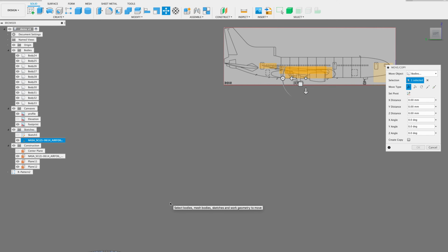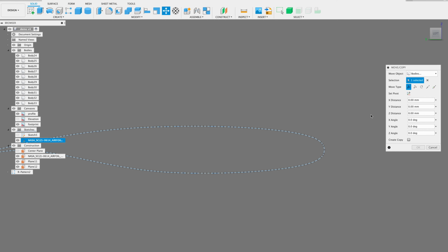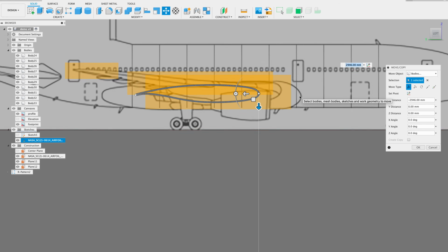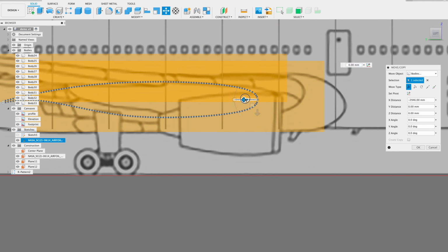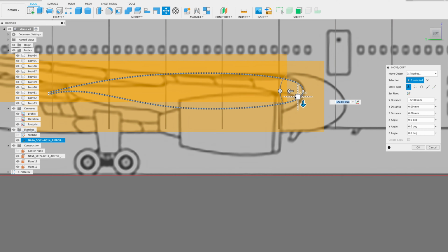So what I want to do is zoom in to this sketch, and select the pivot point, which is done here, set pivot. So I'm going to select that, and then I'm going to press the very leading edge node, and once that's done, hit done. And now you've got this where you actually can move it where you want it. So I'm going to move this into place. We're going to zoom in here, and now I'm going to position this right there.